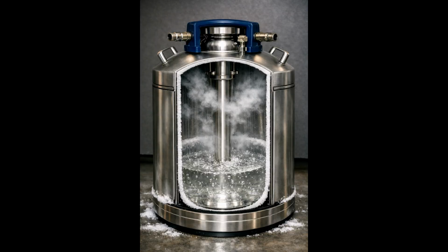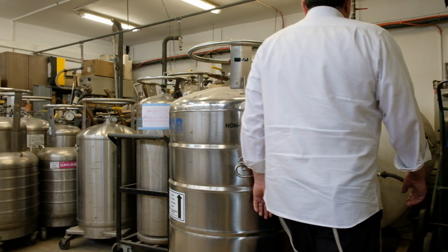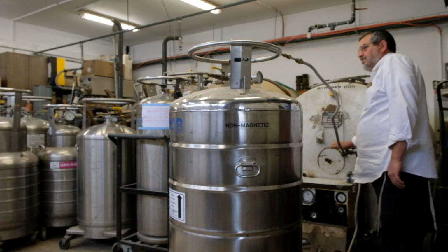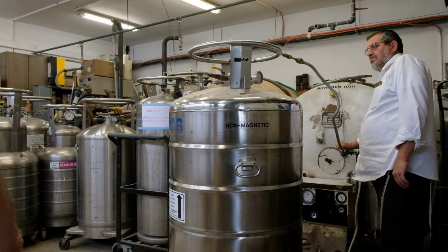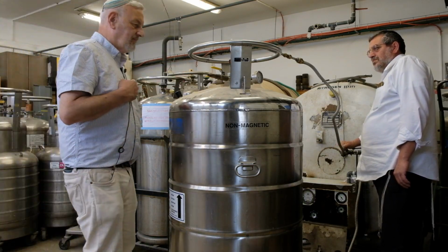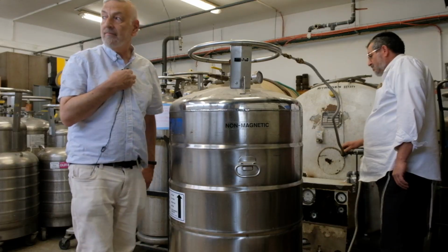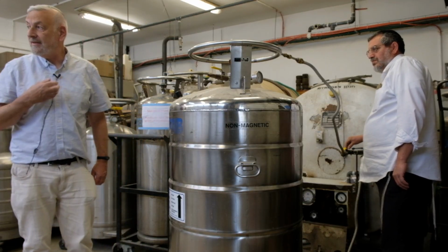When transferring liquid helium, we must consider both gas displacement and boil-off losses. The best practices for transfer efficiency are: 1. Displacement awareness. The receiving dewar contains helium gas which must be accounted for when calculating liquid fill. 2. Minimize boil-off. A warm dewar accelerates helium vaporization, reducing the amount that remains as liquid. 3. Pre-cooling dewars. Cooling the receiving dewar before transfer reduces immediate losses.